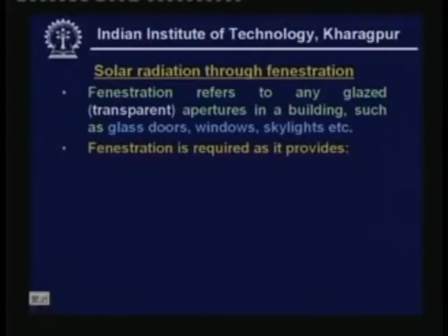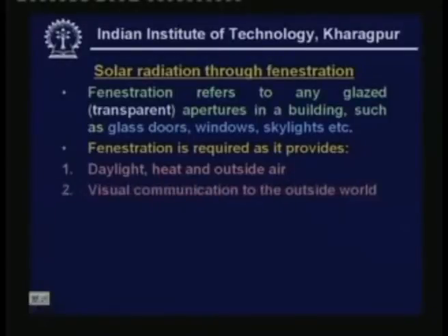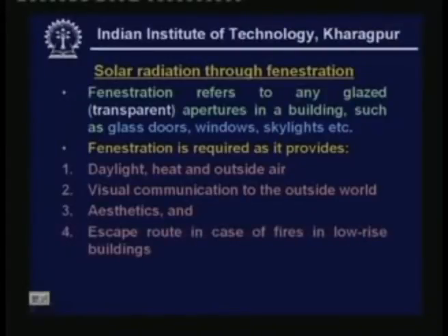We need fenestration, all buildings have fenestration. Why do we need fenestration? It is required because it provides daylight, heat and outside air, and fenestration also provides visual communication to the outside world. It also improves aesthetics, and finally it provides an escape route in case of fires in low rise buildings. Because of all these factors, almost all buildings will have some amount of fenestration. That means you will have some amount of glass windows or glass doors, etc., because of the 4 reasons mentioned here.